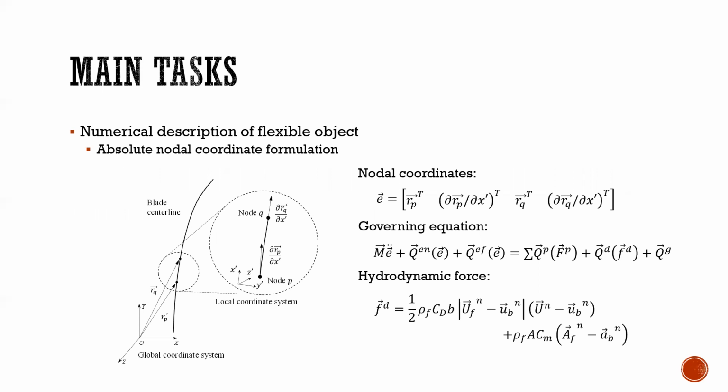In the following, I want to talk about the main tasks of the project. So the first one is to establish the numerical description of the flexible object. In this one, I want to use the finite element method called absolute nodal coordinate formulation. And here is a picture showing the geometrical definition and the mathematical description of the forces in the system. So I'm going to use this to simulate the motion and the forces of the flexible object.